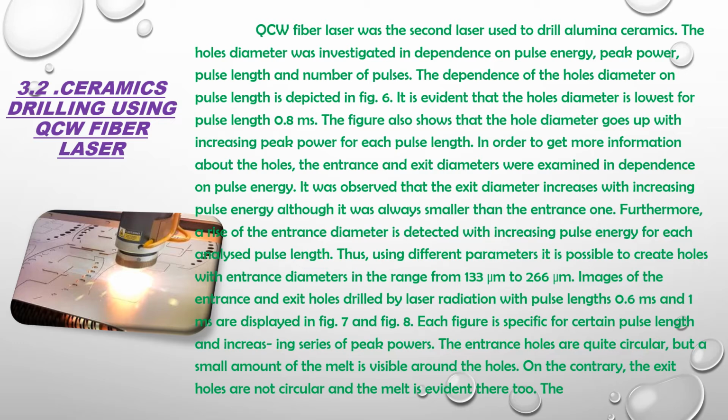Thus, using different parameters, it's possible to create holes with entrance diameters in the range from 133 to 266. Images of the entrance and exit holes drilled by laser radiation with pulse length 0.6 ms and 1 ms are displayed in this figure. Each figure is specific for a certain pulse length and an increasing series of peak powers.